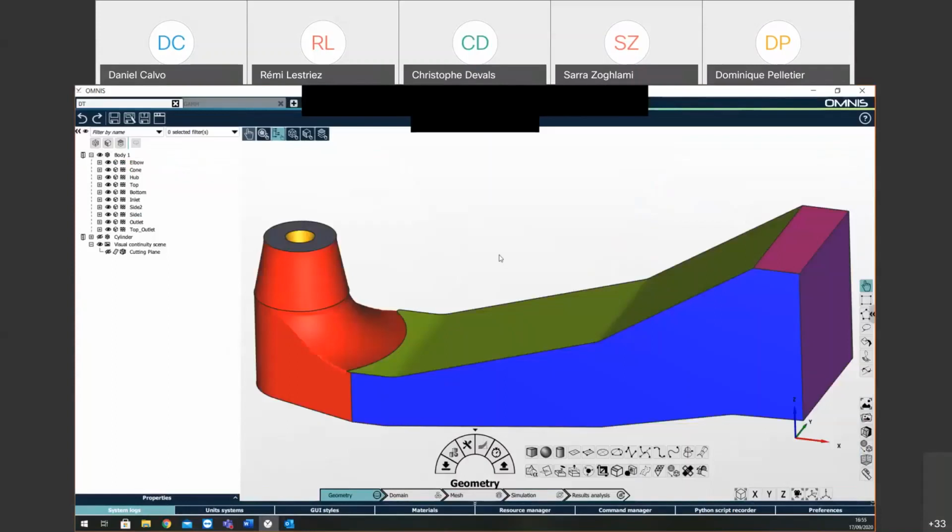What we're going to do is mesh a draft tube. So this will be after the turbine. There will be this draft tube. And the first thing again will be importing the geometry, which is already done, but it's pretty simple. You just import. You're careful with the triangulation. You perhaps specify a maximum size for the triangles, and also ensure that all the regions that have curvature have enough triangles so that they are captured well with good resolution on the tessellation. Because if they are not captured well with the tessellation, then they won't be with the mesh.